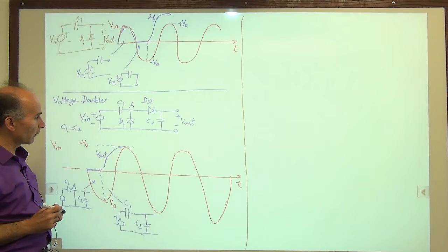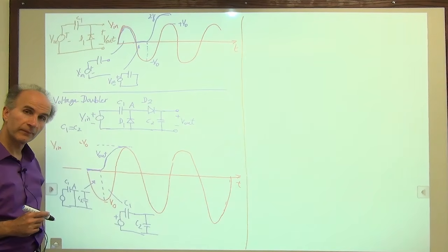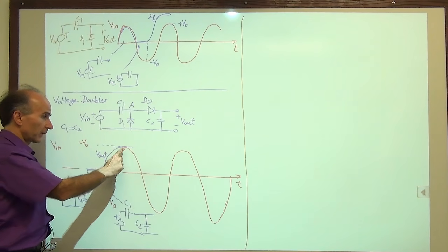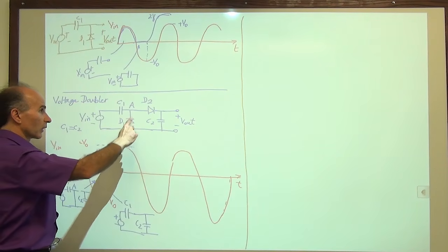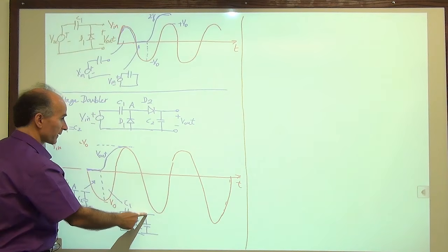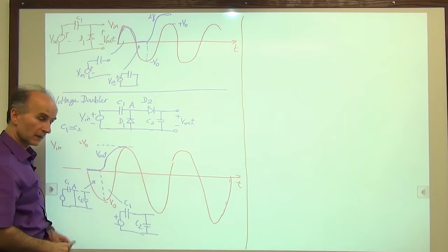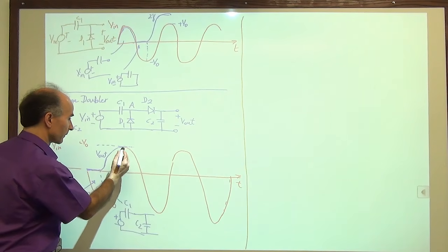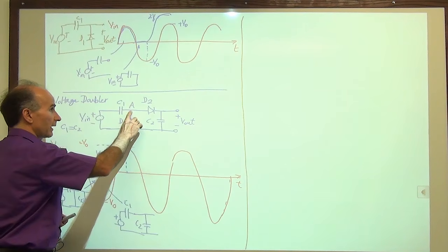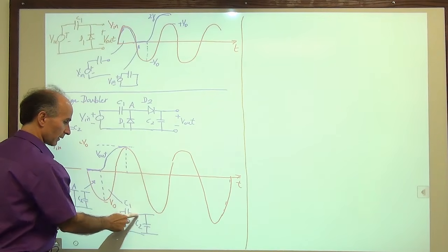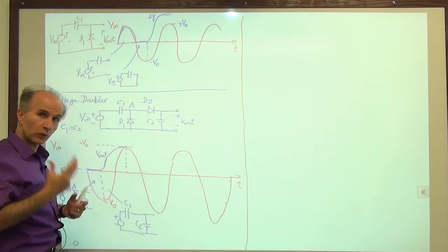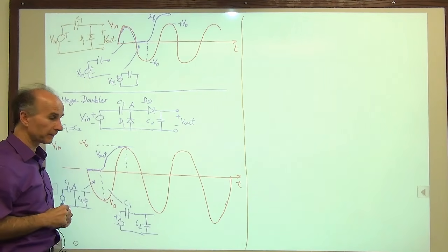All right. Now what happens if the input wants to go down? Okay, so the input wants to go down here, from its peak value. And what we observed is that because A and the output were shorted together, they are both sitting at a value of V0. So we are right at this point in time. The output is at V0. A is also at V0 because D2 is a short right here. The question is, as soon as we start going down, what happens? We have two diodes and we have to worry about both of them, right? Do they turn on, do they turn off, etc.